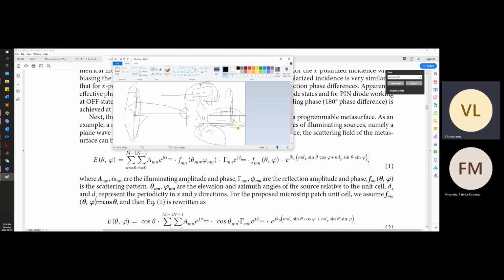So it is traversing some distance within the substrate, or because of the structure it is following some routes and comes over here and comes back. So what is it experiencing? It is experiencing some kind of phase shift, or we can say delay. In the time domain we call it delay, but in complex numbers we call it phase. Delay and phase are almost interrelated parameters.